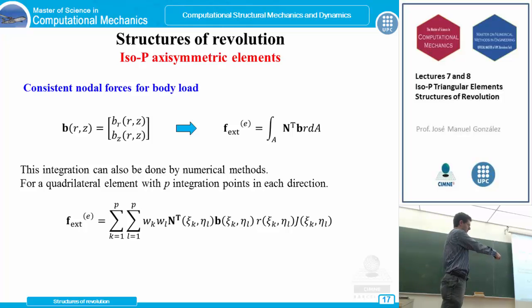These ξ and η components are the location of the Gauss integration points for every Gauss integration point, considering this double summation. So we find a stiffness matrix, a consistent nodal vector for body load, and the same thing with the tractions. Now we have all the ingredients to solve the problem, to find our primary value in these nodes where the nodal values are placed.